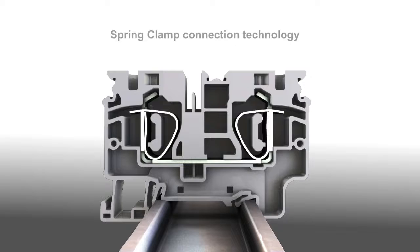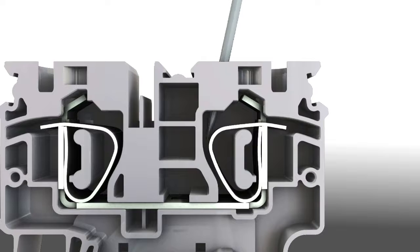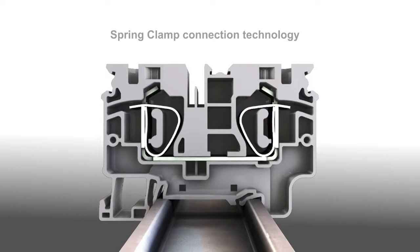So how do I operate a spring or cage terminal? I insert a screwdriver into a slot on the clamp that opens up the preloaded spring. Once my wire is inserted into the open terminal, we remove the tool, and then the spring force presses the conductor against the current bar, and this is how I have a safe and secure connection in less time than I would have on a screw terminal.